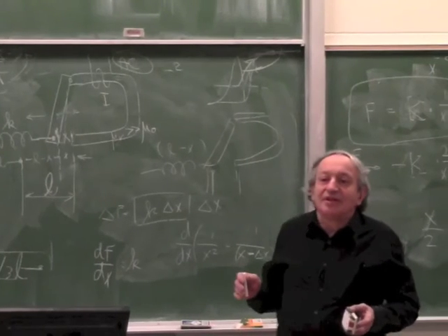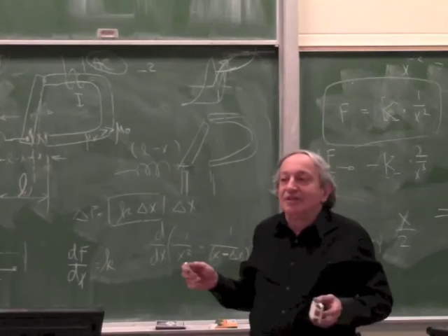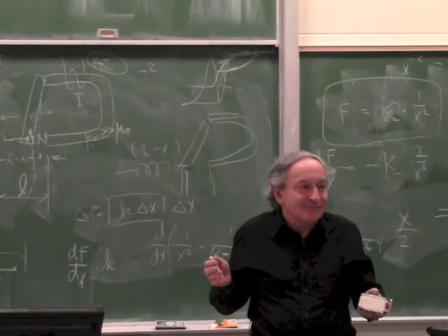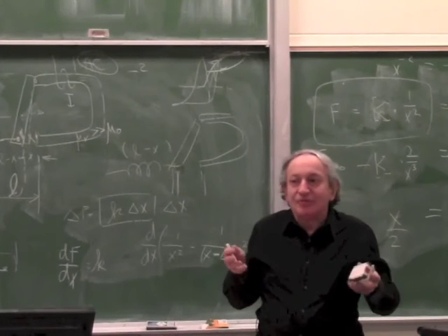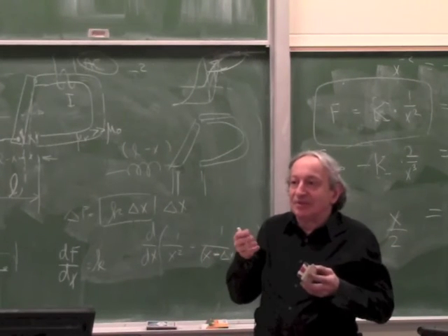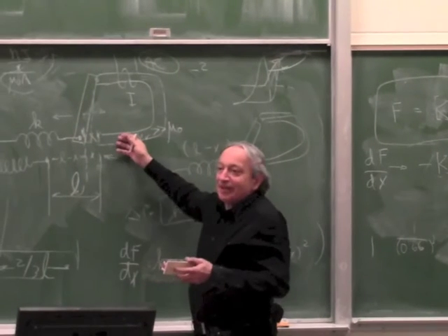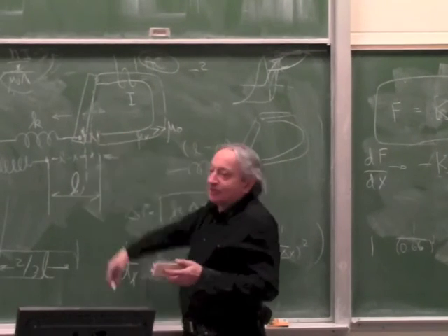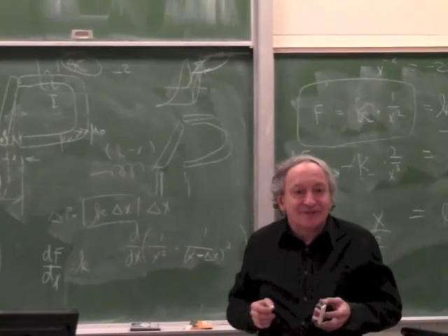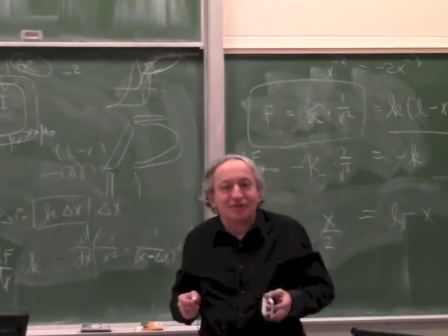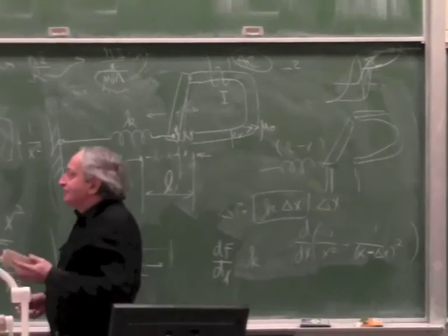Because sometimes there are some reasons. For example, you need like infinite overdrive. Moving iron, you can overdrive it to infinity, it will just saturate, nothing bad will happen. Another example where the actuator has to be vented, like open to the air, moving iron will not collect metallic debris or magnetic debris, because as soon as you stop the current, it stops being a magnet, so all the little particles it collected will fall out. So there are some circumstances where you have to use moving iron. But apart from that, don't use it for a servo, because as you can see, it's a problematic actuator to control.